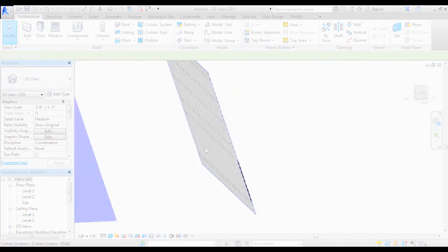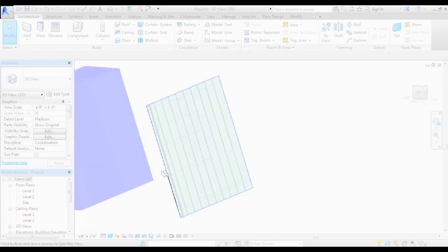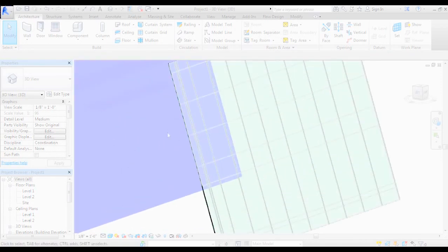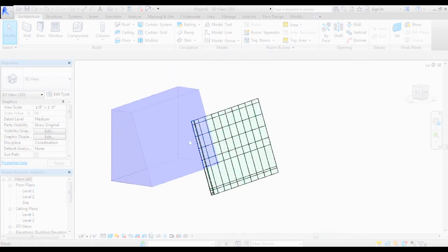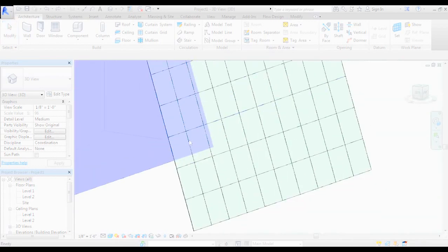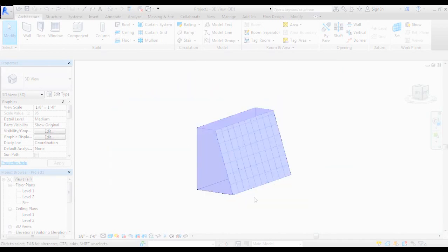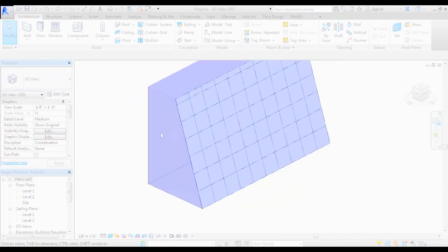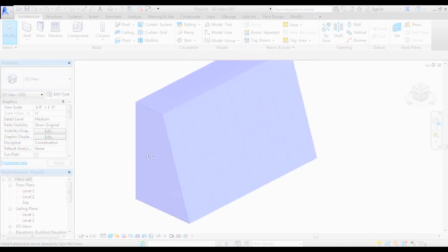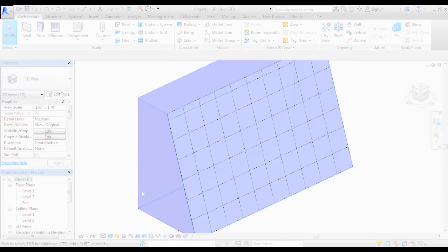There would definitely need to be some structure associated with these mullions on this vertical, but that's another lesson for another time. So the last thing that I might do, I'm going to undo here just a little bit, just to bring that massing object back so that those two are in the same plane. If I also have glass wrapping around this edge, one of the best ways to build that is to use the same massing component to build this face right here.